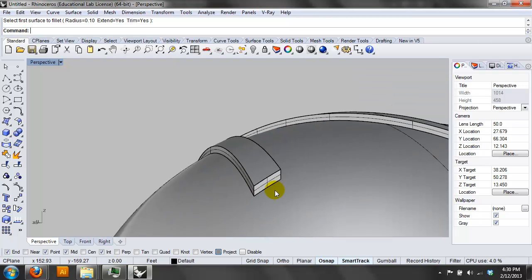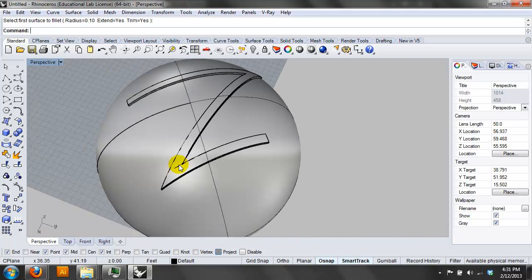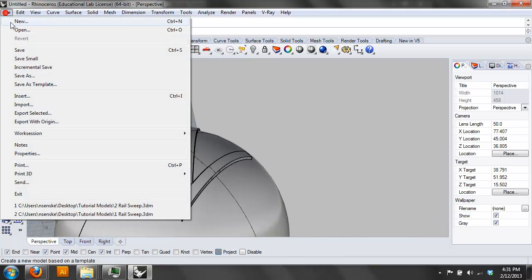But maybe you could do fillet edges, and then that would look like it's embossed on a surface. So if you have a label or something on your device, or a button that follows the contour of it, you can project that two-dimensionally onto the geometry, or even just do an intersection of it, and then extrude it, and then fillet it, and you've got that nice button. We'll talk more about this next time. But anyway, project is another really useful technique.